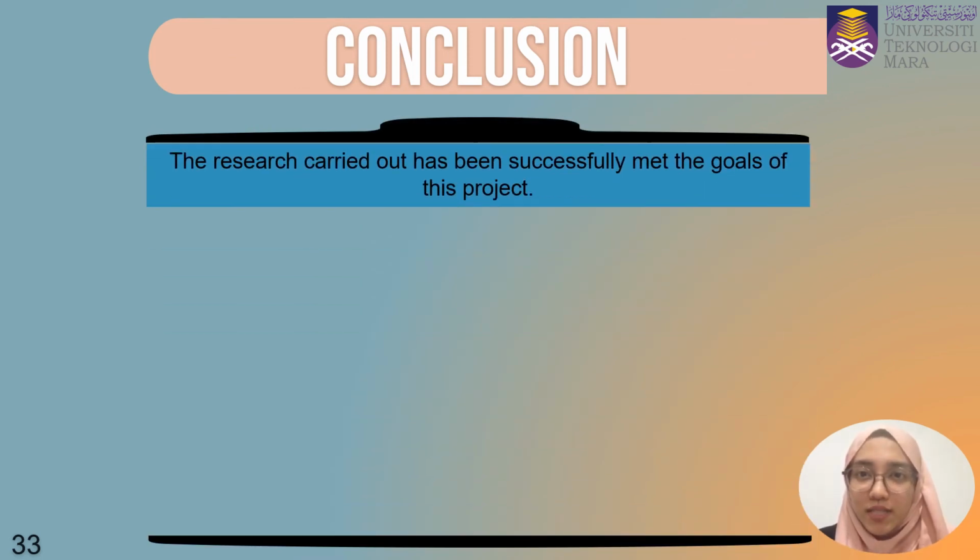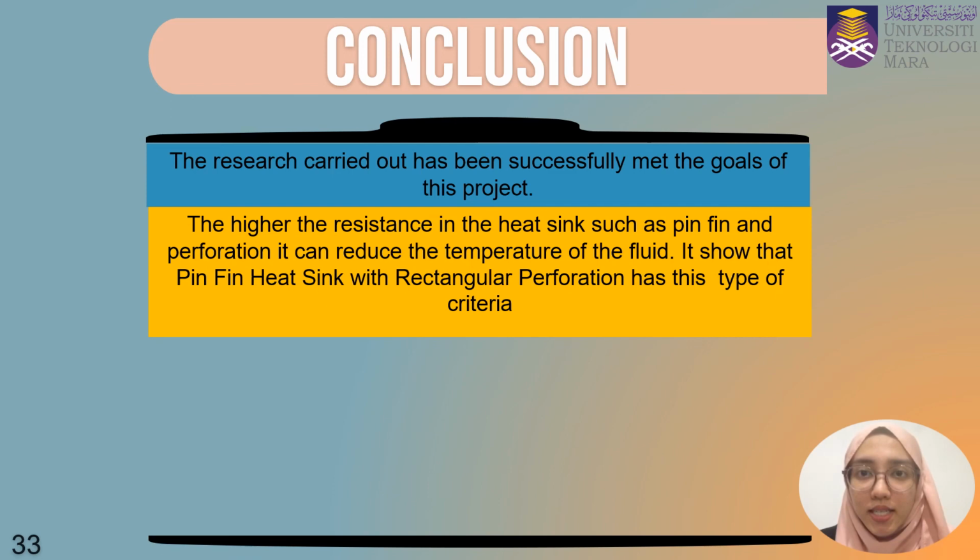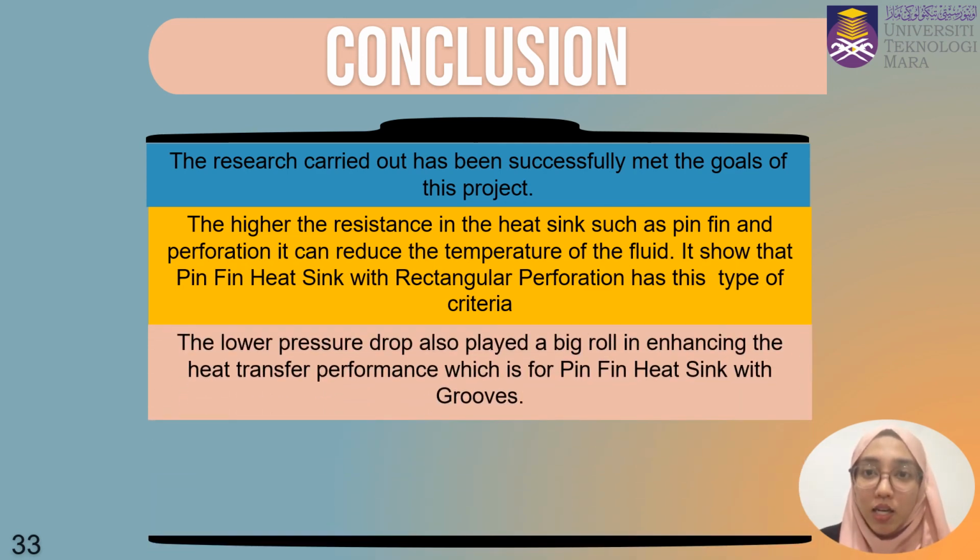The conclusion from this study is that the research carried out has successfully met the goal of this project. Then, the higher the resistance in the heatsink, such as the presence of pin fin or perforation, the more it can reduce the temperature of the fluid. It shows that the pin fin heatsink with rectangular perforation has this type of criteria. Next, the lower pressure drop also plays a big role in enhancing the heat transfer performance, which is the case for the pin fin heatsink with groove.